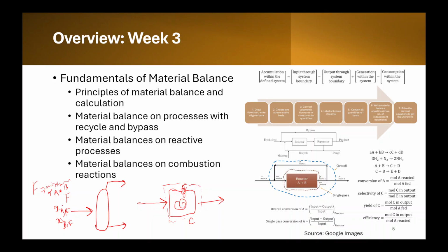The concentrations can be expressed in different forms. You saw that, suppose this is in mole percent. But here the concentrations are given for the D stream, or distillate, and this is the bottoms. So xA comma D may be in mass percent, based on the problem statement. You have to convert it to one basis.